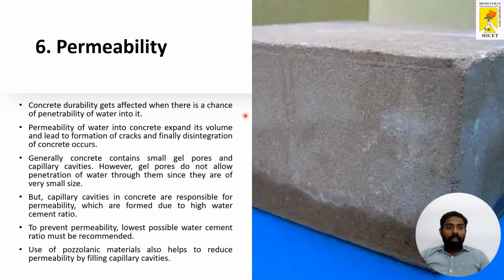Next one, permeability. The concrete durability gets affected when there is a chance of penetration of water into it. Permeability of water into the concrete expands its volume and leads to the formation of cracks, and finally disintegration of the concrete occurs. Generally, the concrete contains small gel pores and capillary cavities. However, gel pores do not allow the penetration of water through them since they are very small in size, but the capillary cavities in the concrete are responsible for the permeability, which are formed due to the